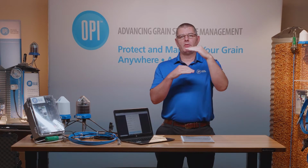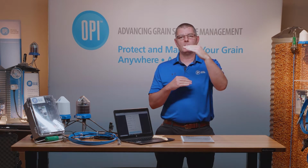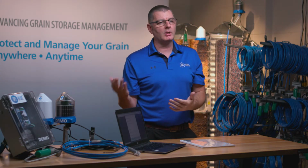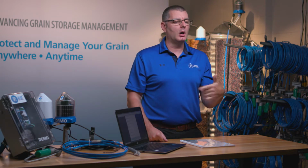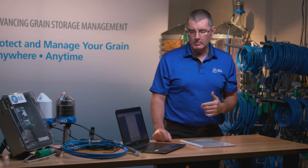You want to make sure that if the conditions are just in and then they fall out, your fan is going to run for a certain amount of time, whatever you set it to, or is going to stay off for a certain amount of time before it turns back on. So the fan's not cycling off and on, off and on. That's really hard on the equipment, and we want to make sure we don't abuse the equipment in any way.